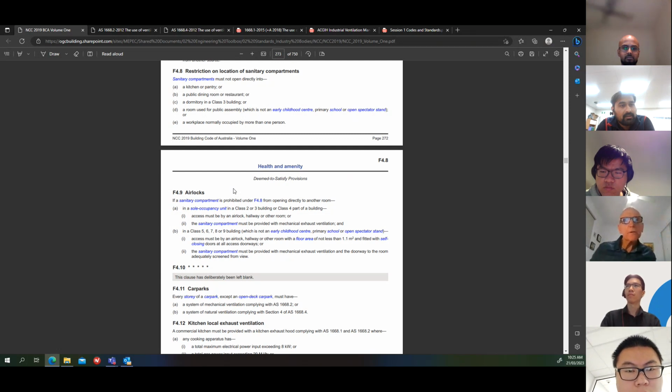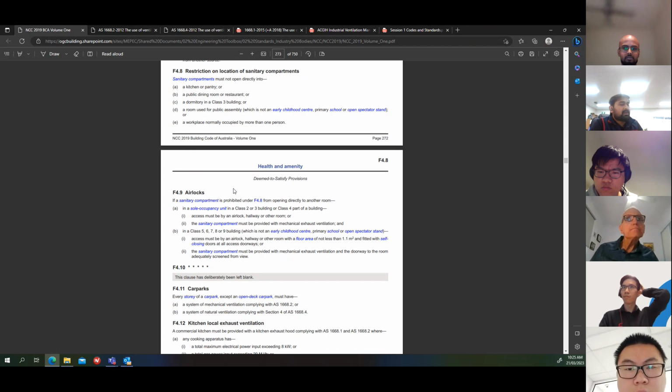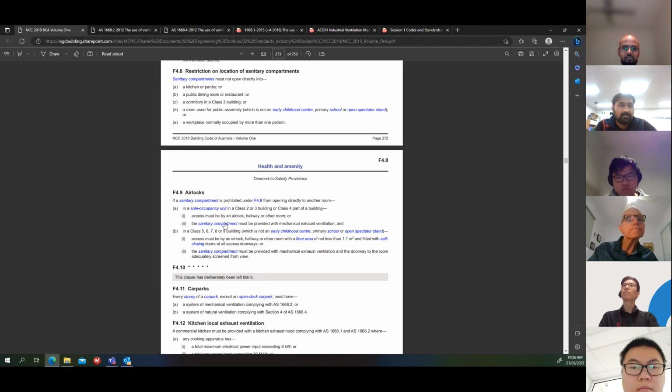That's a little bit tricky to work out. I think AS1668 Part 4 would give you some guide there. What sort of building is it? It's a community center and open space for the functions. So I have almost 50% opening in the window. So as of now, I consider 50% from the windows and the other 50% I worked out based on the capacity and the pressure requirements.